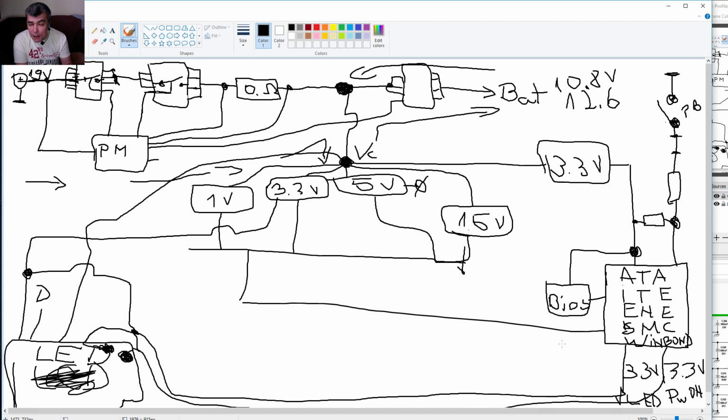Of course, if the screen has light, I would say it's 100% a screen issue. If the screen has light but no picture, or lines, the next thing I will check is the external screen. You have the external VGA connector or HDMI. You just plug in and check on the external screen.